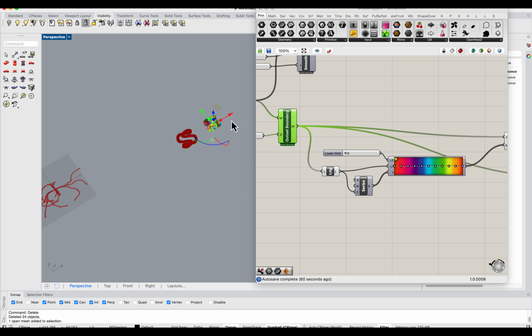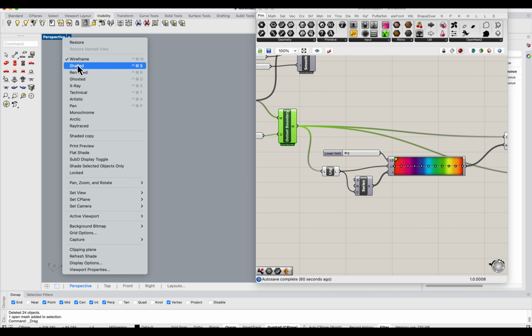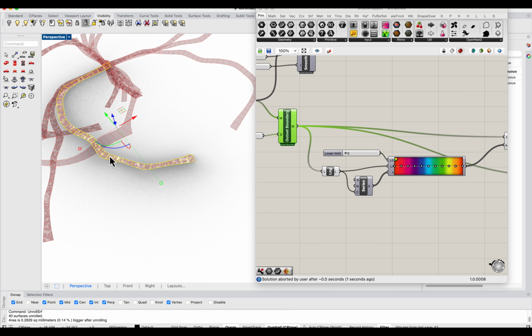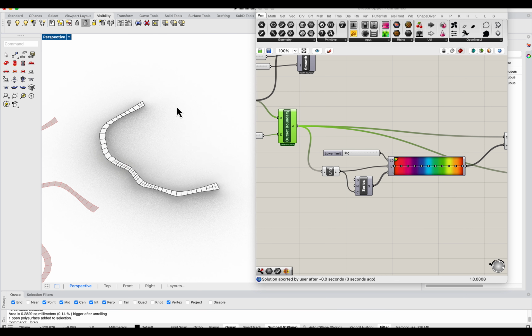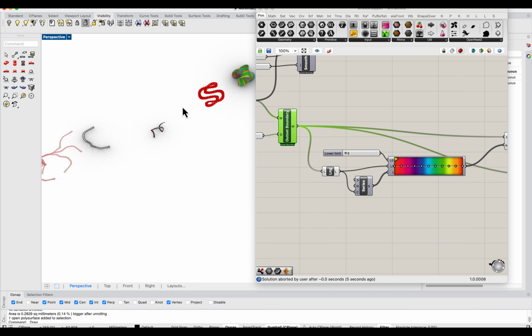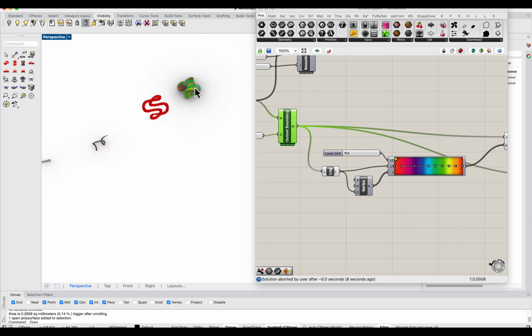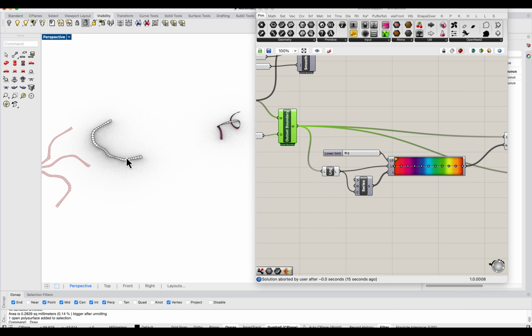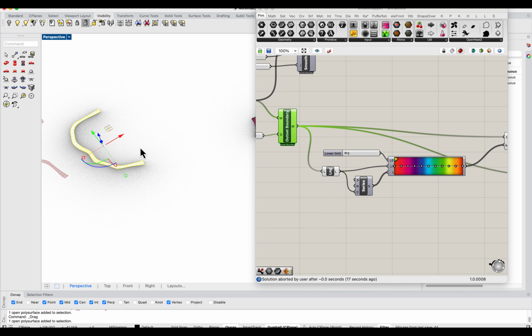So let's say I grab this mesh. I first do a mesh to NURB, because we cannot unroll the mesh. And then this one can be unrolled, right? So without exploding it, and that will give you this type of strip. And I'm basically automating this sort of operation. So I'm just converting each mesh into a B-rep, a boundary representation geometry, and then unrolling them individually. And then this could be processed for manufacturing purposes.